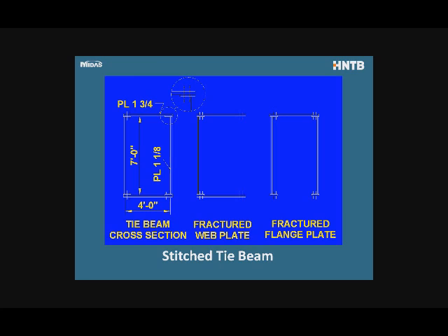It's a pretty expensive approach to do these bolt lines. For example, in case of Blennerhassett, it added 140,000 bolts to do this. In Europe, they don't do this. They just build these things, but it's kind of considered cheap insurance. So this is a very common detail in the US.